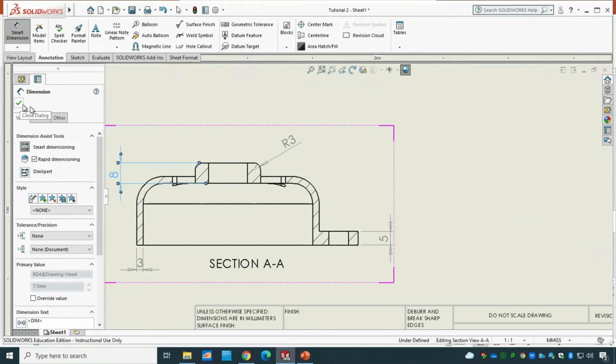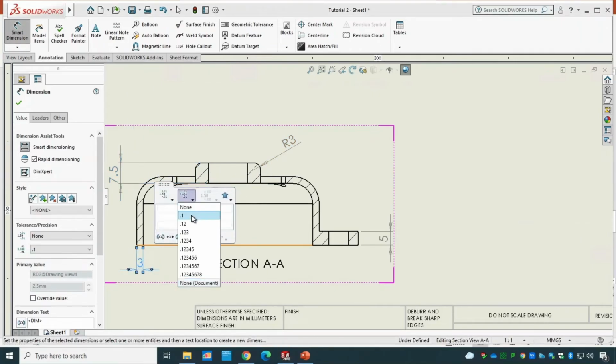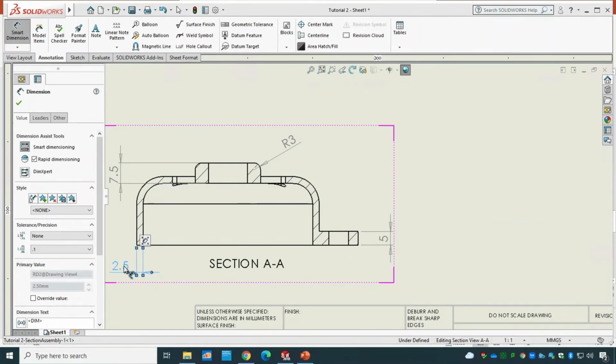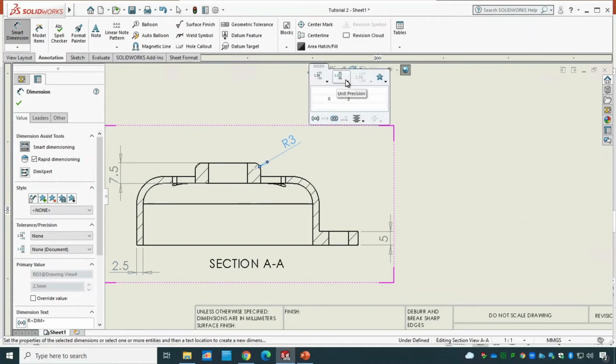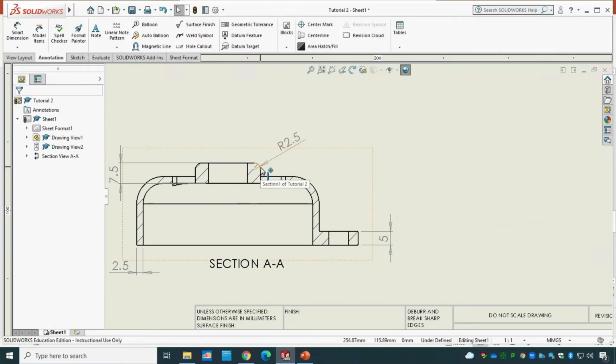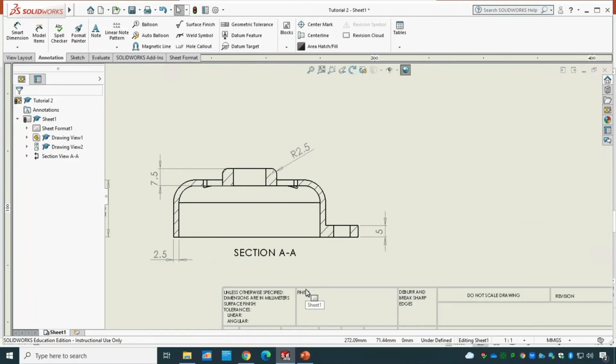and you will see that it's trying to round these, whereas what has happened is this one is 7.5, so let me bring one decimal, so you can see this one is 7.5, this one also is, let me use one decimal, 2.5, so that's why the numbers are different from what you will see. Okay, let me see what else we have. Let me double check again. Yeah, this one also is the 2.5 for that fillet that I have there. So this dimension is fine on that side.